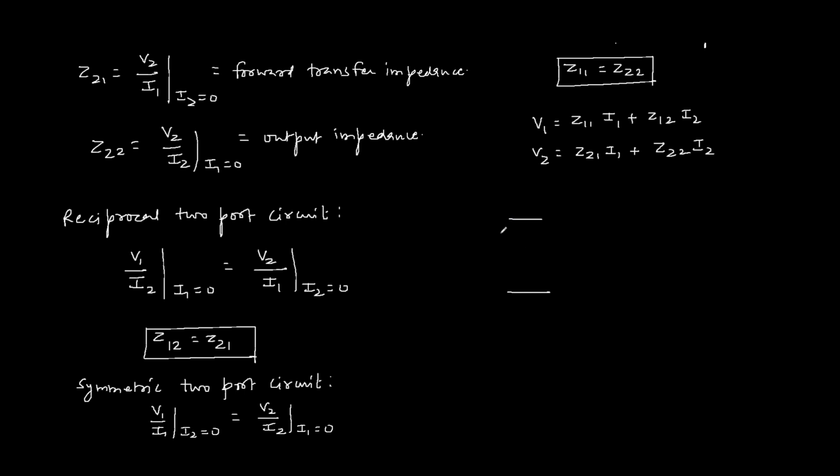So this is the voltage V1. In the right hand side of equation we have two terms, and two terms have to be voltages, and here we have the addition of two voltages, means these two components are connected in series. Z11 I1 is the voltage drop for input port or port 1, and Z11 is the impedance. So the impedance is here.